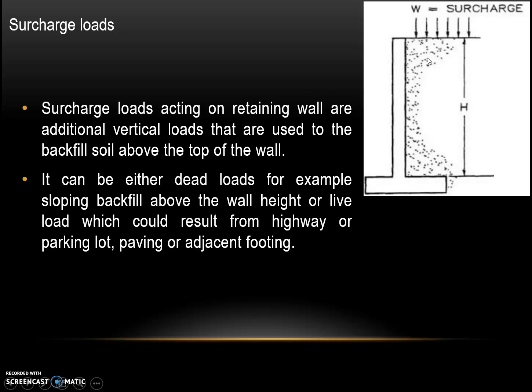Now we will find out what we mean by surcharge. Here we can see a retaining wall of height h and there is a surcharge, which is shown with the help of arrows. The surcharge loads acting on a retaining wall are the additional vertical loads applied to the backfill soil above the top of the wall. Here the dotted portion represents the backfill soil and on top there is a surcharge.